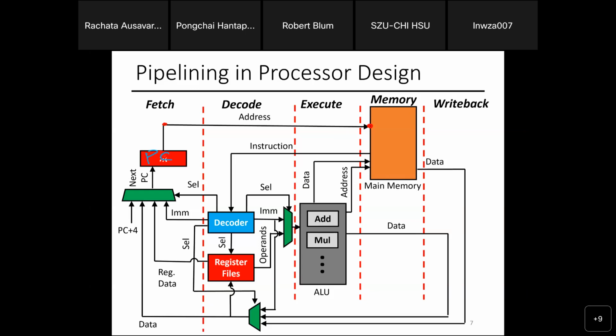My problem is, when I'm doing a pipelining design, how many instructions can share that wire? More than one. Let's say right now instruction 1 is here. I am done with fetching, and right now fetch is on instruction 2. Instruction 2 is fetching right now, right? It basically means that I have one program counter. So what value does it take? Should it take the old value from instruction 1 or the new value from instruction 2?